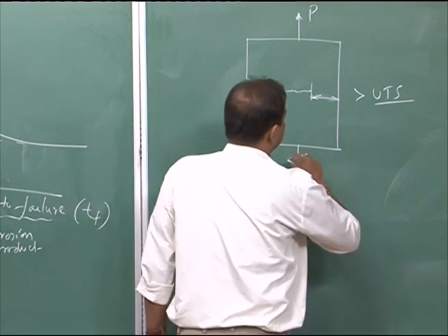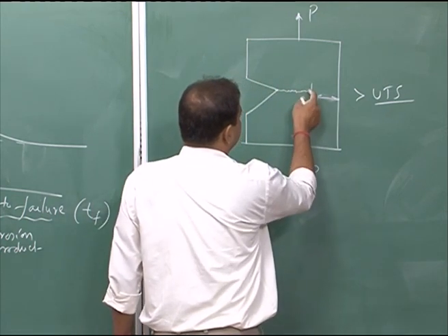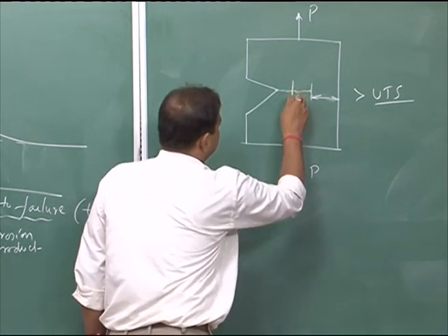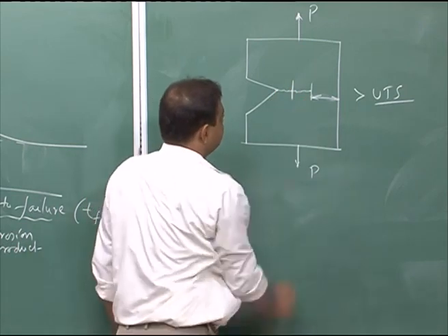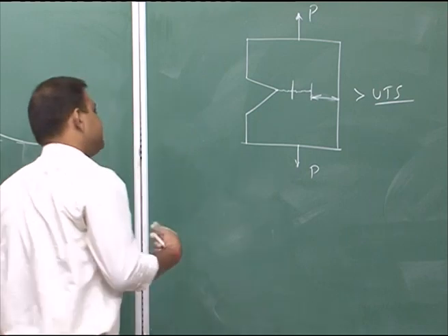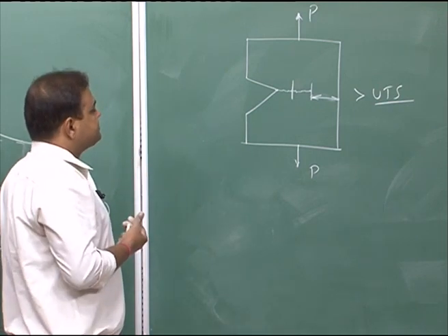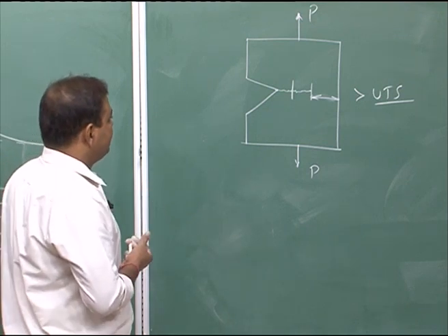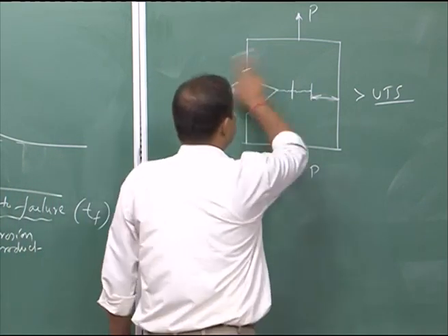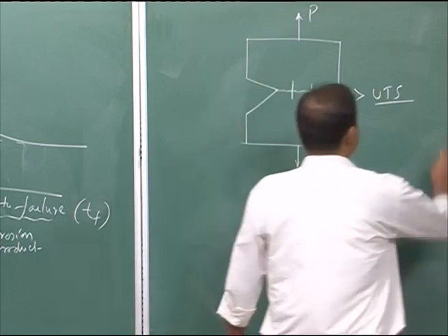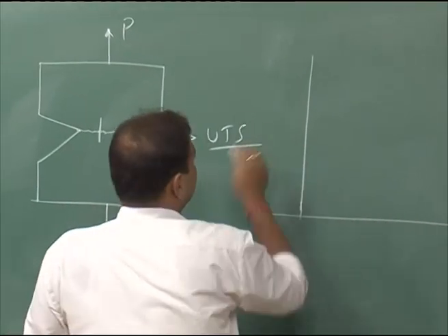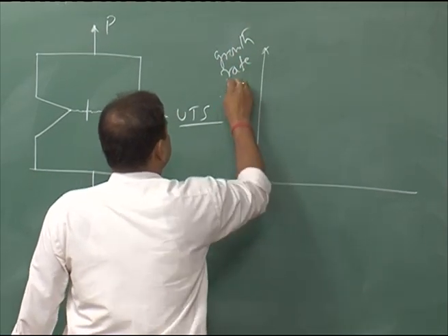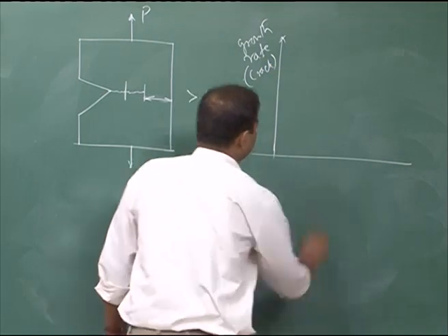Okay. So, that means unless we check the total time to failure, we would not be able to judge, for example, up to this point the metal has gone and then we stop the experiment, whether the material would have a very good SCC resistance or whether it has a poor SCC tendency. So, that way we need to understand the total time to failure. For that, let us say I would like to plot the growth rate of SCC crack with time to failure.